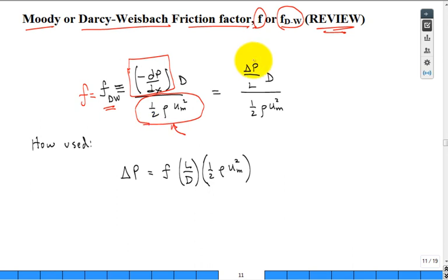Now, sometimes they'll write it like this. What happened to the minus sign? It's gone. Where's the dP dx? Gone. But if you go back and think, here's that pressure as a function going from 0 to L. That's dx. So here you go from here to here. The pressure change they're talking about is a positive pressure drop.